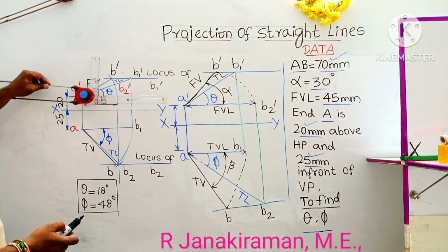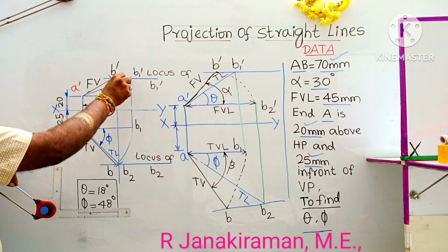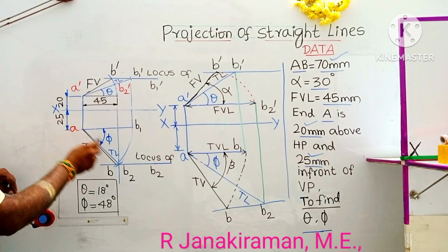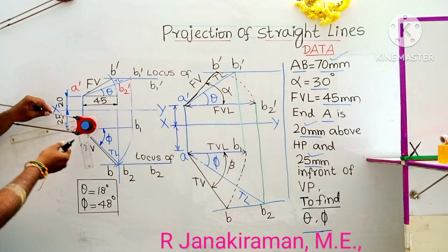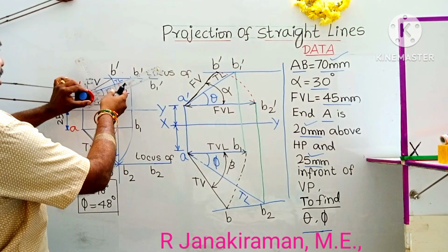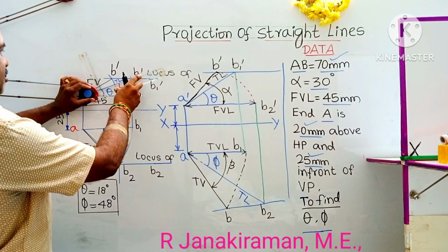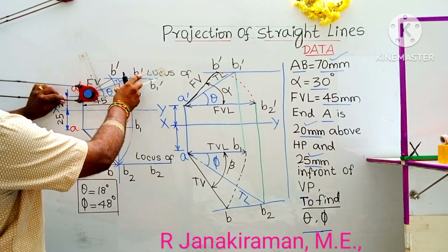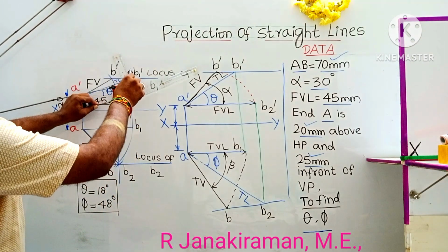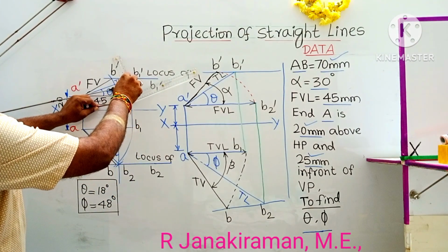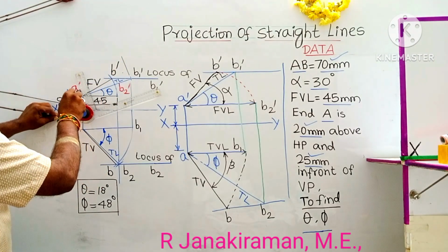Let us dimension this true length. What is given as 70 mm is A'B1'. Similarly, AB2 is also a true length. Release your drafter scale, rotate it anti-clockwise, and keep the longer scale edge over the line A'B1'. Rotate anti-clockwise, the scale will be tightened and positioned like this. Draw an extension line from point B1' using the shorter scale. Similarly, from A', draw an extension line.